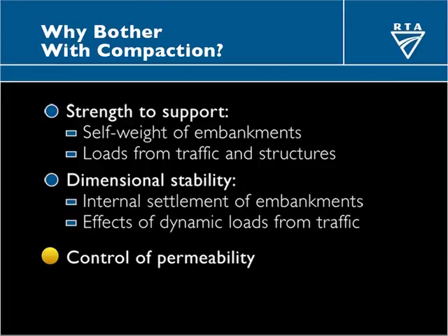And lastly, particularly for pavements, we're looking at control of permeability. That is the ability of water to get into the materials and reduce their strength. Obviously, the more compaction you've got, the less permeable the material will be.